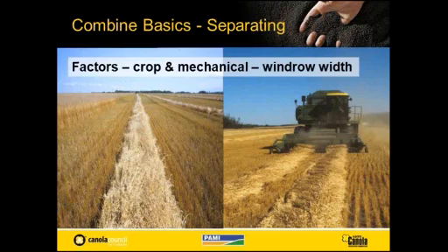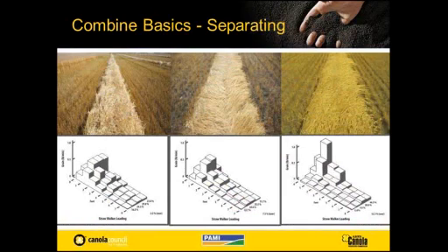As I mentioned before, in terms of how you feed different combines, it's important. Now, when we talked about the single rotor, rotary combines are less sensitive to the formation of the windrow, whereas when we get into conventional combines, it's important to recognize that the formation of the windrow can have a huge impact on the separating, simply by the distribution of where the grain is going.